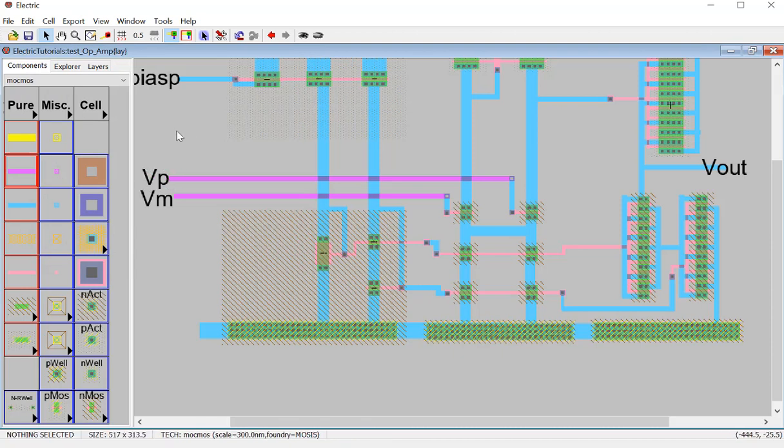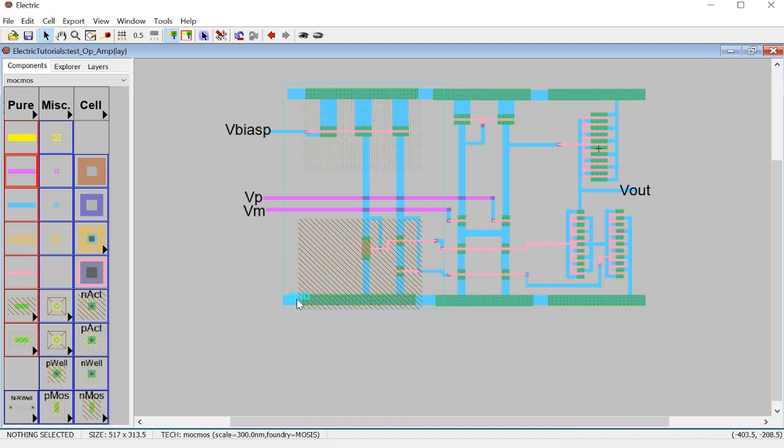All right, so these are all the ones I need to do a ground as well. And here's another thing, because all these pins are in metal 2, I want to make it consistent. That will make metal 2 for all these pins. So that's VDD, right? And I will make a metal 2 node and connect to there, connect to here. No, go to metal 2. Connect this guy to here as a metal 2. Metal 2.